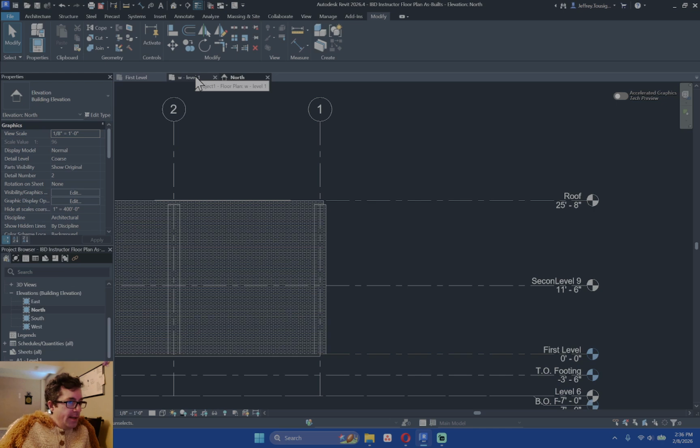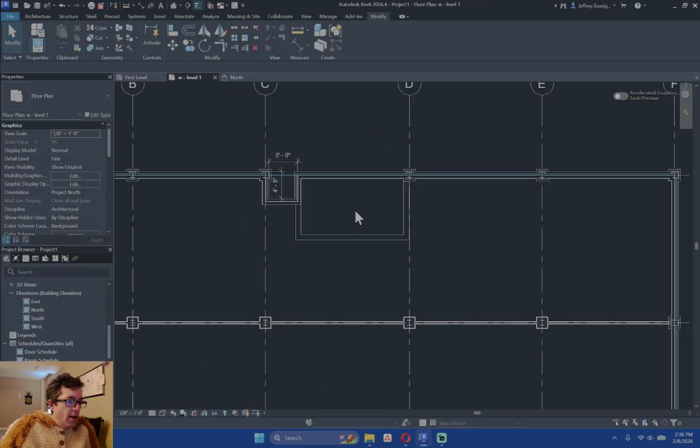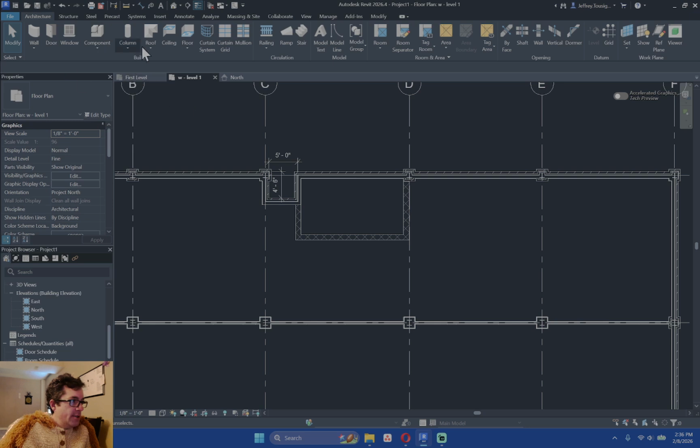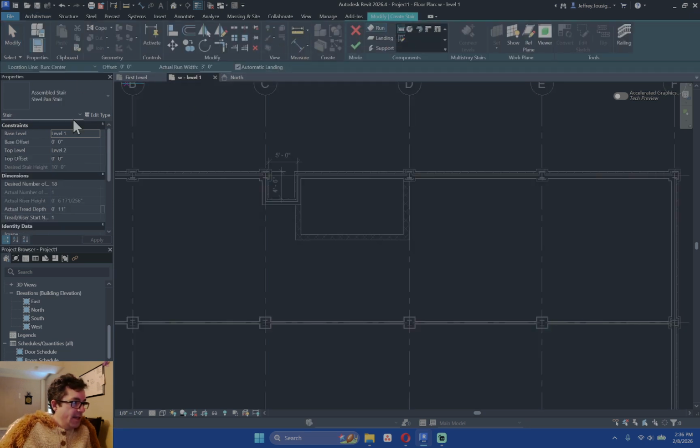Yeah, I think we're not going to change the heights, but we are going to consider that if we are actually drawing stairs in here, let's just have the stairs tool do its thing. We have stairs going from first to second floor, and we have the run height of 6 and this nonsense, 171 over 256. You are so close to half an inch, but that's fine. It does the math, not me. And then I'm going to have the depth just maintain at 11 inches because that, again, is worst case scenario in terms of how much footprint we're going to have to leave for this stair.